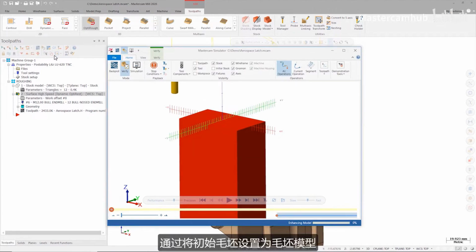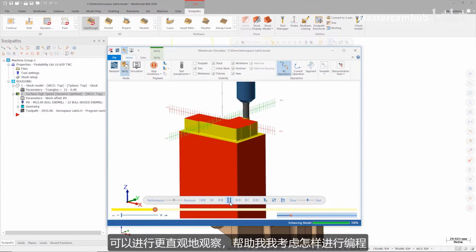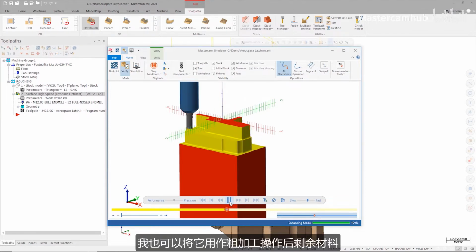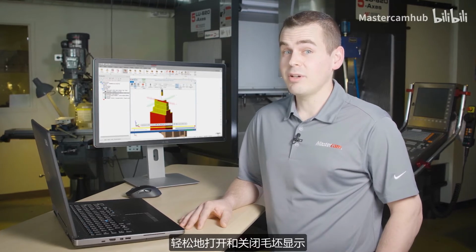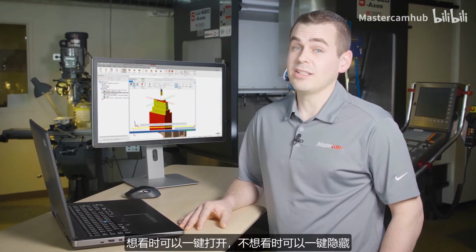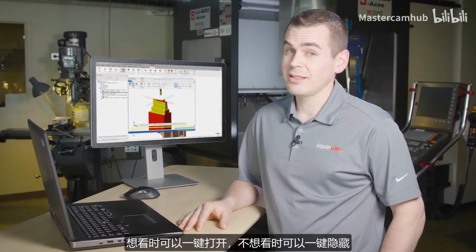By having my initial stock setup represented as a stock model, it gives me a great visual representation which helps me when I'm thinking about how to program the part. I'm also able to use it as rest material for my roughing operations, and I can use it as the stock definition in simulation. And since I can easily turn on and off its display, just like any other operation in the Toolpaths Manager, it's always there when I want to reference it and hidden when I don't.